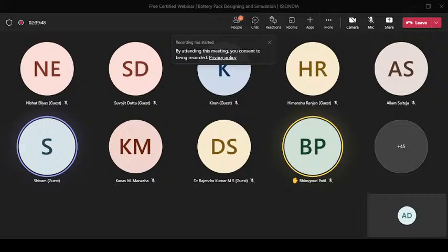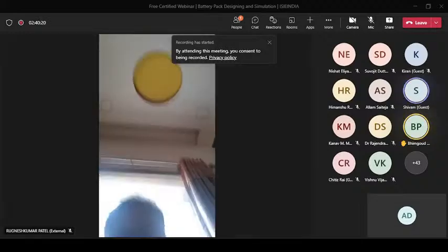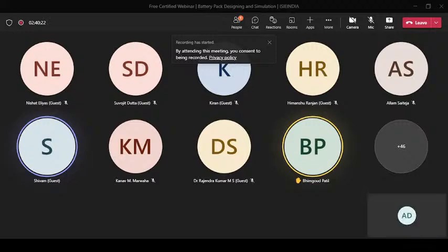For that you will need a third BMS that will simultaneously look into both the battery packs and discharge both of them equally. Each individual battery pack has its own BMS, and if you are connecting it with the external or third BMS, your BMS is continuously discharging the battery pack. Yes. And once the 10 Ah is discharged completely and the 20 Ah is still remaining, what happens in that case? Does one of their circuits get open there?